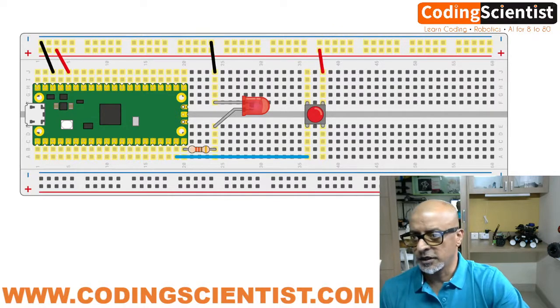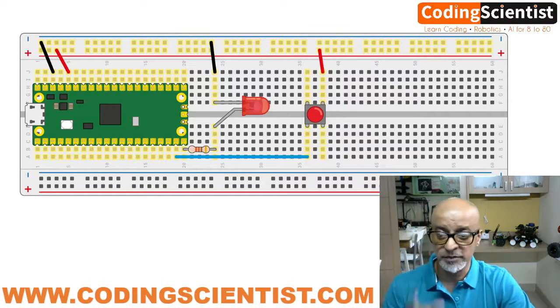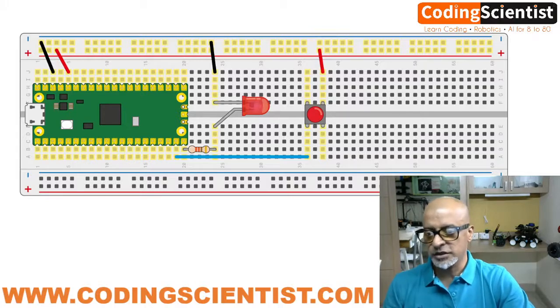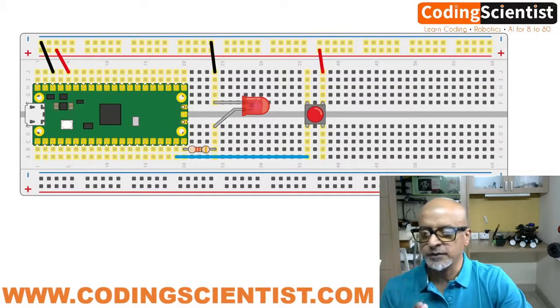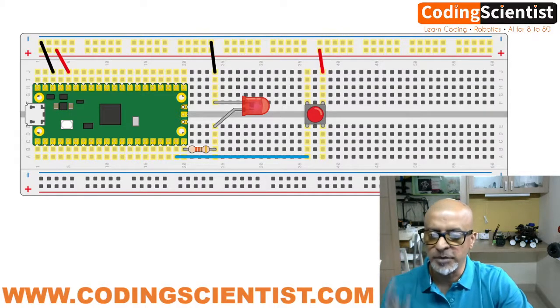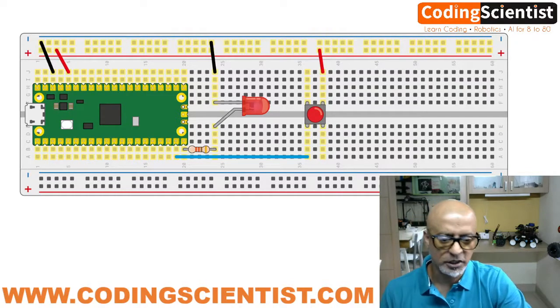We need to click the run button here, the green button on top, run, and there is a pop-up box as usual. You may not be able to see it on my screen because I need to share the entire desktop. I am on a different mode. So in your system, as soon as you click run, it'll pop up a message. It'll ask whether to save the file either on this computer or on Raspberry Pi Pico. You need to click Raspberry Pi Pico. Okay, I clicked on that and I'm saving the file. You can name the file as something like button.